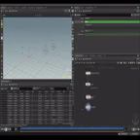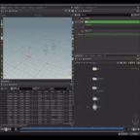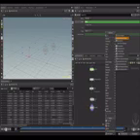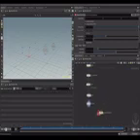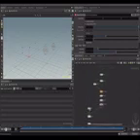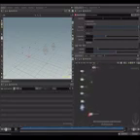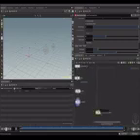So this time, I'm going to use these points to direct the fracture areas, and I'm going to use a Voronoi fracture points. So let's make it here, and we should plug the geometry to the first input, which is the box. I'm going to add the point by typing Alt and left click, and here we go. And the impact points to the second one.